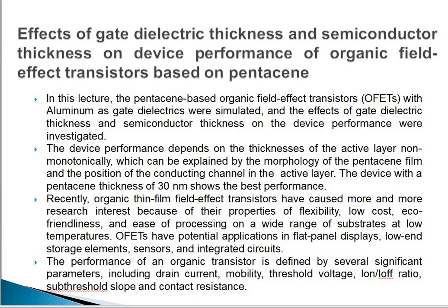The device with the pentacene thickness of 30 nanometer shows the best performance. Recently, organic thin film field effect transistors have caused more and more research interest because of their properties of flexibility, low cost, eco-friendliness, and ease of processing on a wide range of substrates at low temperature. Organic field effect transistors have potential application in flat panel display, low-end storage element, sensors, and integrated circuits.